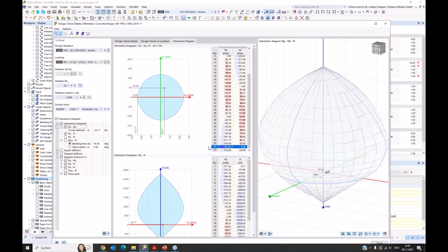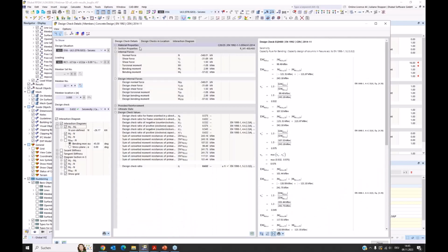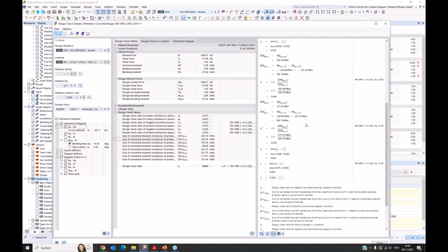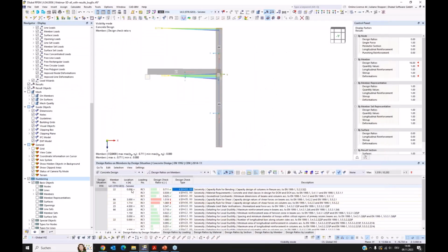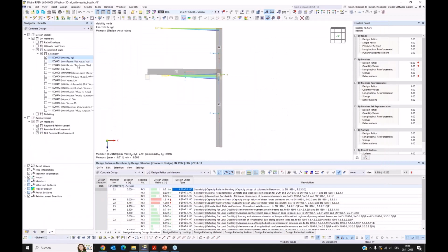and in minus direction the same, as I have longitudinal reinforcement on both sides the same. If I would have different reinforcements here, I would have different moments. So I can come back and we see, yes, our program found the right values for member 22 around Y for the resistance, and here in the other direction. Yeah, and you can do this if you need. You can follow where these values come from. Okay, that's it for the check of the strong column weak beam,